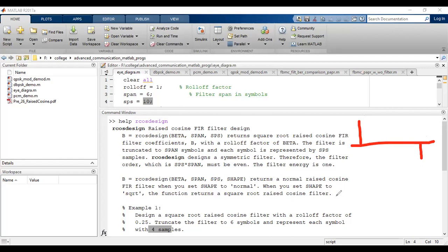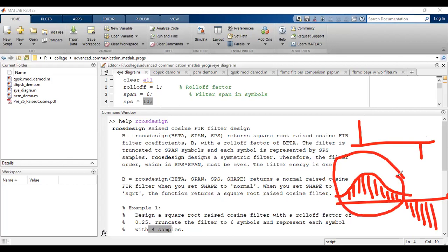This 1 will be replaced by a raised cosine pulse. This pulse is going to contain 1, 2, 3, 4, 5, 6, 7, 8, 9, 10 samples. Then there is a -1, which once again is 1, 2, 3, 4 and so on. This is an impulse, and this particular thing here is the impulse response.